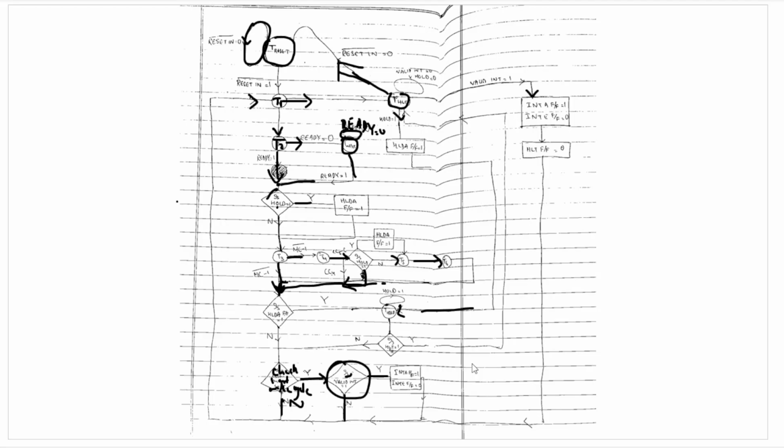Upon execution of the interrupt, the microprocessor will enter the interrupt acknowledge machine cycle. The interrupt acknowledge machine cycle will have its own opcode and its own T1, T2, T3, T4 states. So it will again go back to T1, T2, T3, depending upon what the previous instruction is. Fine. So this is the complete state transition diagram: how the 8085 microprocessor moves from one T state to another, how it remains in the T hold state, the T halt state, the T wait state, and the T reset state.